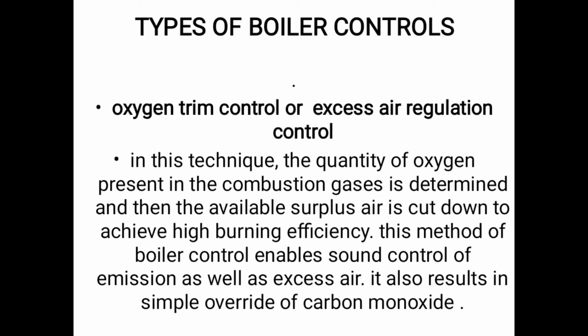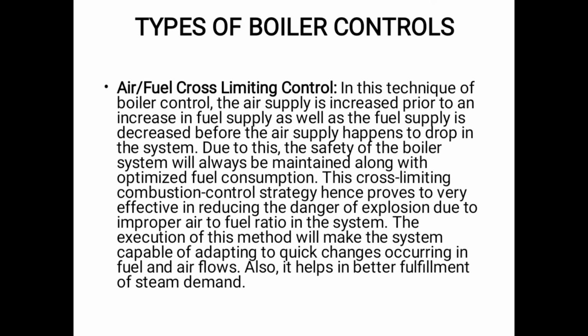As you know, when the excess air increases, then the firing efficiency goes down, because the excess air takes the temperature of the furnace and goes into the atmosphere. So to reduce NOx and improve firing efficiency, oxygen control is very crucial.